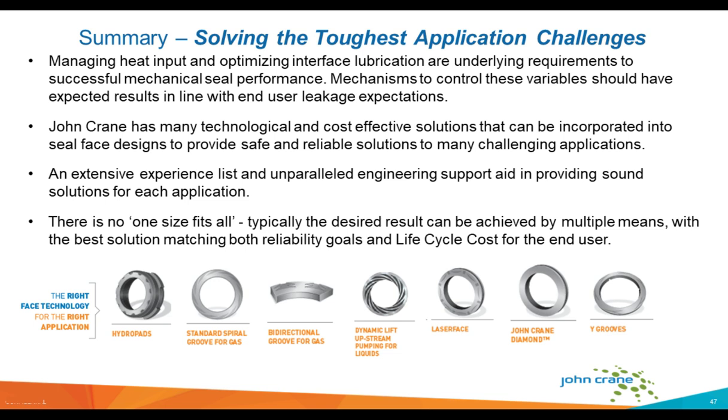So to summarize a little bit, we've talked about application challenges, and the underlying theme here is we want to manage heat input to the seal face, optimize the interface lubrication, and control these variables so we have expected results that are in line with what end users are looking for in terms of leakage expectations. What we want to emphasize is there's no one size fits all. There's no one magic bullet to cover every single application. The devil is in the detail, so to speak.